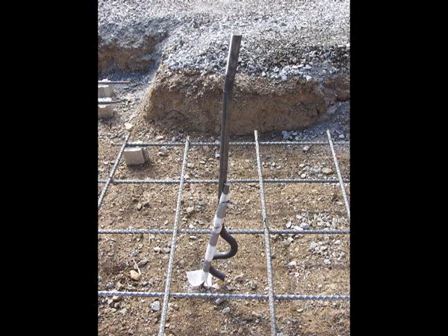Now the key is that you cannot have the anchor bolt touching the metal of the rebar, because the rebar will eventually rust out and that rust will travel up and ruin the bolt in terms of its anchoring to the concrete. So we isolate it here by wrapping it in some foam and duct tape, and then duct tape the bolt to the piece of rebar that's already been wrapped.